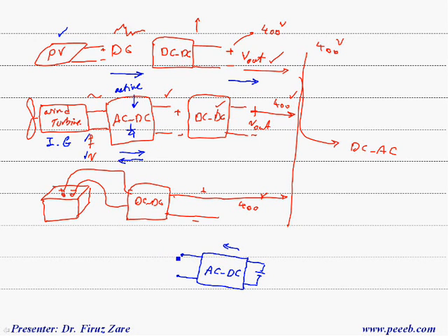In this case, if we have an inductor and we control this current, and if we control the magnitude of current here, that means we can control the power. So with respect to this terminal at any phase angle, it's possible to control the active and reactive power.